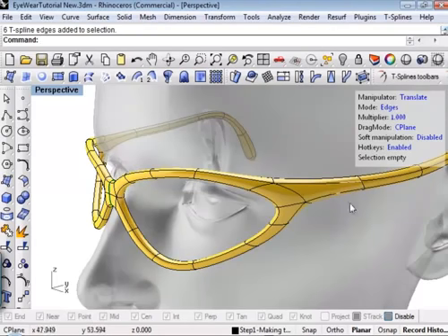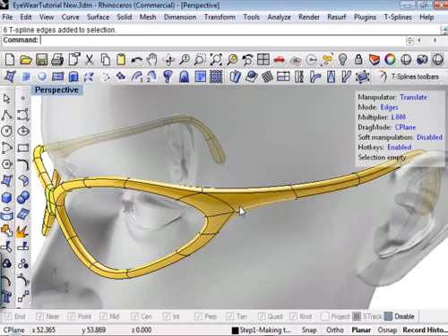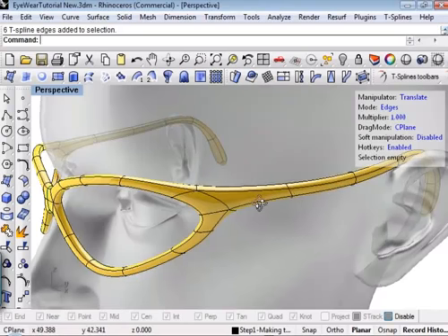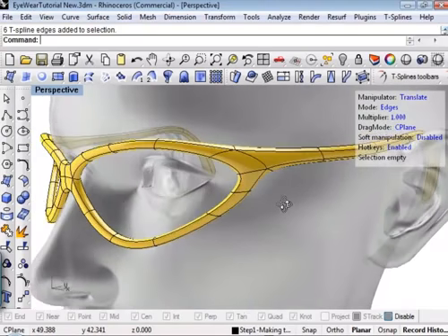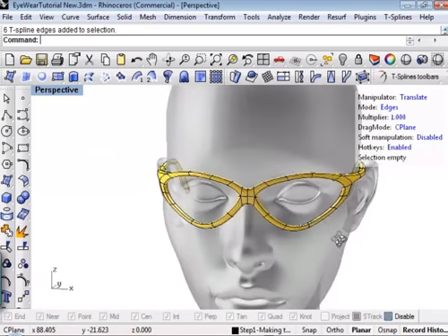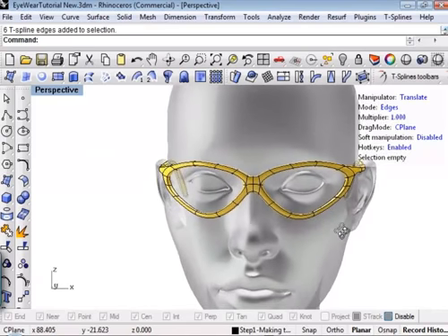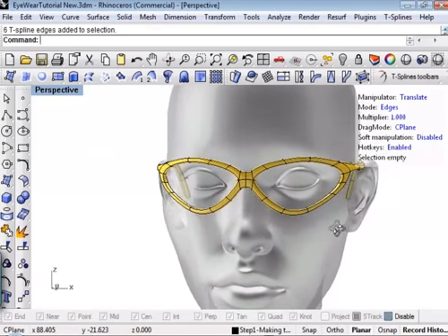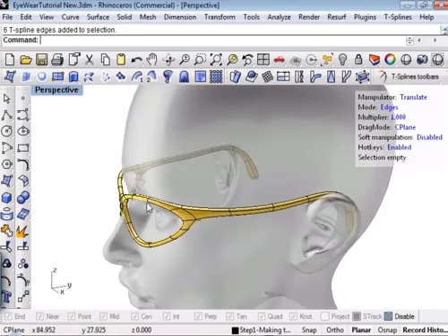We used a couple of Rhino commands to create a curve going in one direction, a curve going in the other direction, combined them, made a Rhino pipe, rebuilt it, converted that to a T Splines object, and then just welded that to here. And you get this beautiful transition. And it looks like under 30 minutes we've created something here that I know from experience used to take me, well, let's just say a lot longer than that to create something like this.